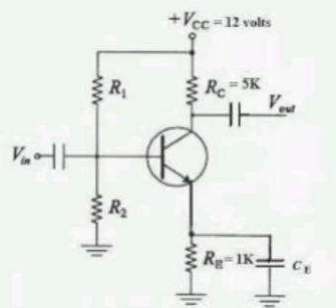Apply the Laplace transform to the circuit. Then 20 ohms is in series with L I naught, equal to 2.5 into 0.5, that equals 1 volt, in series with 0.4 S. So I of S equals 1 by 0.4 S plus 20, that equals 2.5 by S plus 50. Apply the inverse Laplace transform, then you will get i of t equals 2.5 e power minus 50t for t greater than or equal to 0.